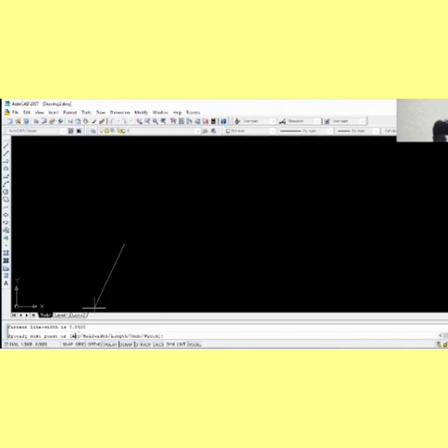Now other things that we can specify here, we have arc, we have half width, we have length, we have undo, and then we can choose any option that we want. For instance, let's choose width. So if you want to choose width, all we just need is to pick the first letter of width, which is W. So you now type W and then press enter.